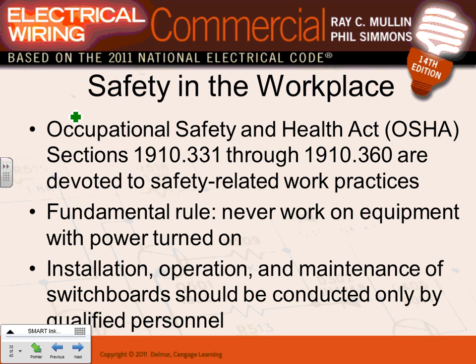Okay, the last thing, guys, is OSHA. You are not electricians, but OSHA will require you to de-energize before working on equipment. You de-energize, you work on it, right, Jeff? De-energized work, lockout, tagout procedures. That's the requirement. If you're a project manager and somebody's going to go over the panel, we almost killed an apprentice here in Dunwoody because of that panel. Working at the Mall of America, almost burned his face. You know what I mean?